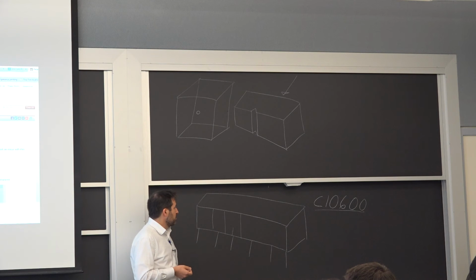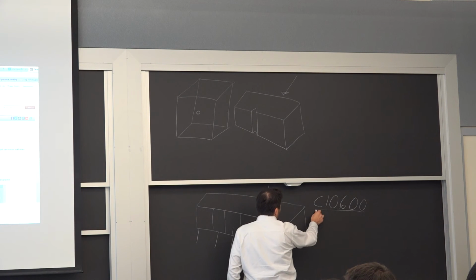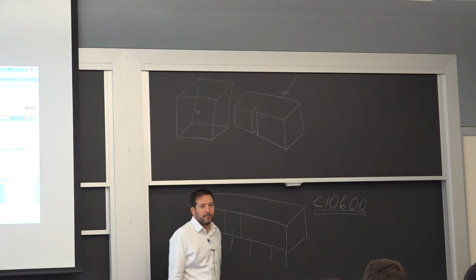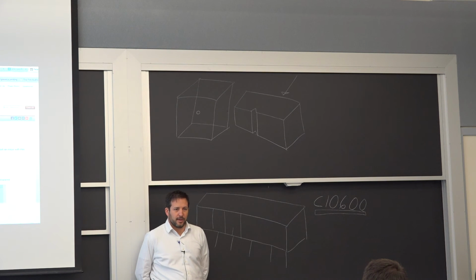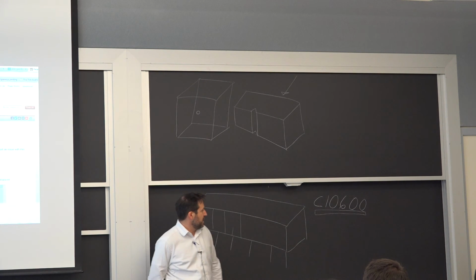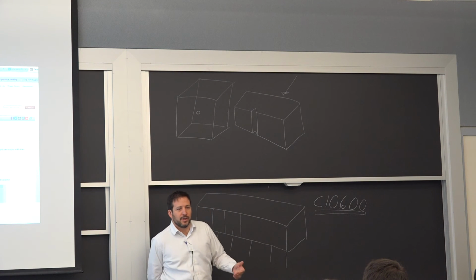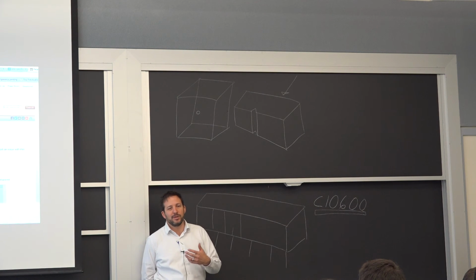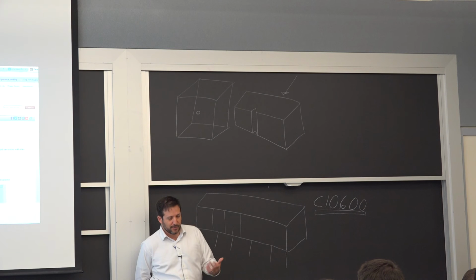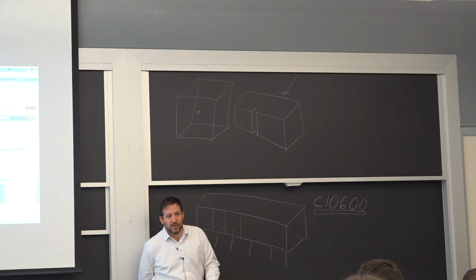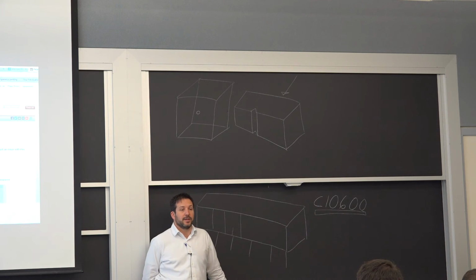So in this project, really, and it was a big design firm that had probably all the expertise in-house to know how to do better. But they didn't because the engineer in charge didn't appreciate enough the difference between saying which alloy I want versus which properties I want. So there were multiple ways. It could have been a slightly different chemistry, to tell you the truth, but there were multiple ways, even with that alloy, to cast and heat treat it in a way that it would have done just fine for this application.